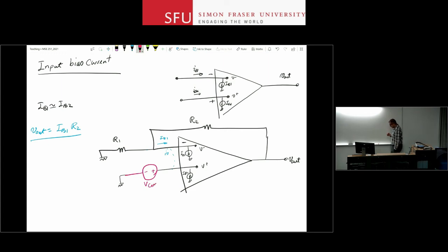That is going to be large enough for the same value that is needed to make the output 0 under these operating conditions. So how much should this V correction be? Well, where does that voltage at the output come from? IB1 flew through R2. That's the reason I have a voltage at the output. If I make all of IB1 go through R1, I will not have that problem, right?